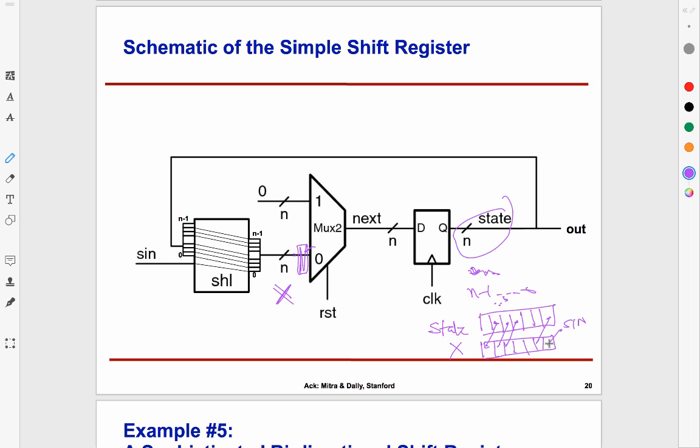Now, in a computer, when you do a left shift operator, it's presumably using some logic which does something like this, right? I mean, arithmetic left shift versus logical left shift with feeding some bits into the LSB location. It would probably be using some hardware like this. But we are in the world of hardware right now, right? And at the hardware level, a shift is nothing but taking the content of the register and feeding it back into the register with a skew of 1.